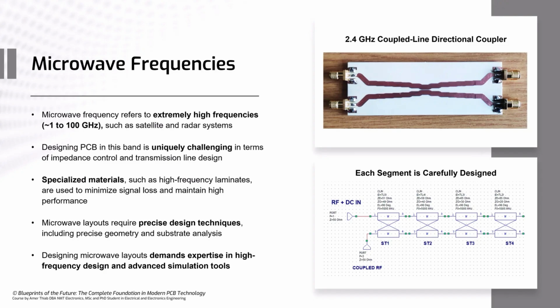However, look at the schematic at the bottom showing a part of it. Nothing is simple in designing such a simple device. The substrate as well is not standard FR4, and it should be considered to achieve the required performance. Microwave layouts require precise design techniques that include geometry and substrate analysis. They demand expertise in advanced electrical engineering topics and have dedicated simulation and EDA tools.